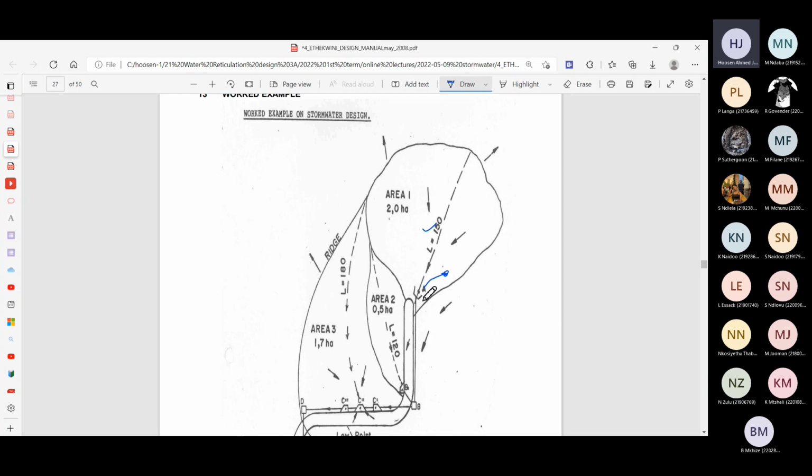You're getting runoff from all portions of your catchment. So if you took, for example, a 5 minute period, then the runoff at this point in 5 minutes time would be at point A, but the runoff from that point would not have reached A as yet. That runoff might still be sitting somewhere down at that point over there.